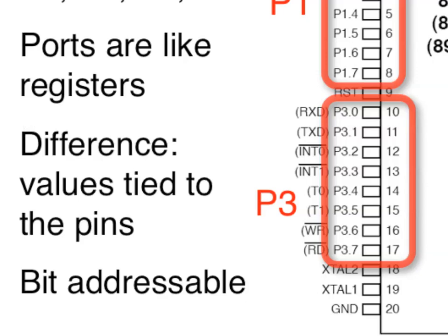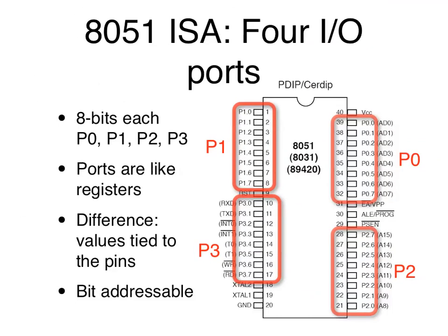So yeah, those are for other secondary I/O functions that are not general purpose I/O. And the rationale is that you might not need all of these general purpose I/O pins. When you don't, then you can use those unused pins for their secondary functions.